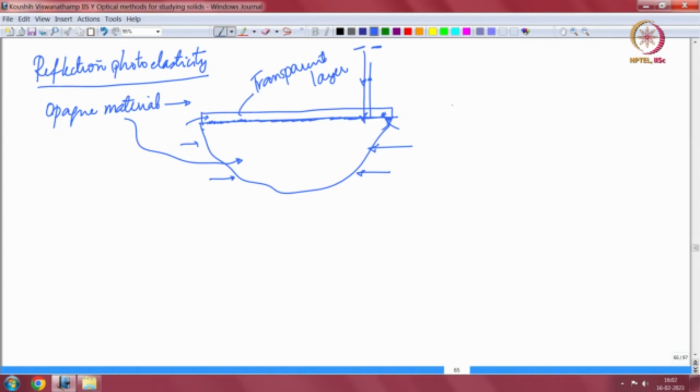So, there is usually a very mild angle that is given. So, you actually need a fair distance from the imaging system to the surface. You will often see people use high zoom lenses for doing reflection photoelasticity, and this small deviation gets amplified over a longer distance, and you have an analyzer polarizer pair again as usual, and you finally see what the reflected field intensity looks like, okay.